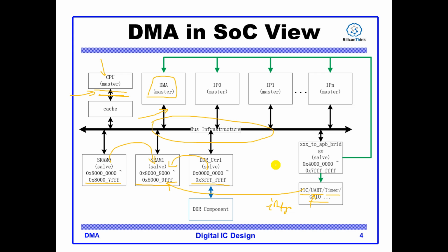So you can see here, to receive 1000 characters from UART, if we use the DMA controller, the CPU just configures several registers inside this block. Then the DMA controller will talk with UART and copy the 1000 data from UART to an internal memory location.